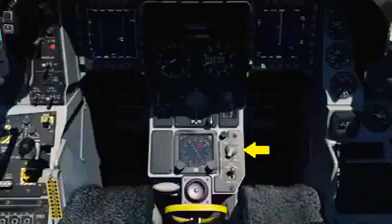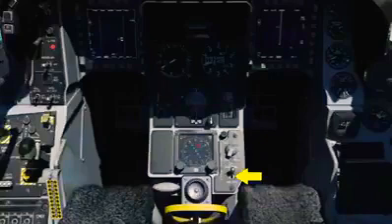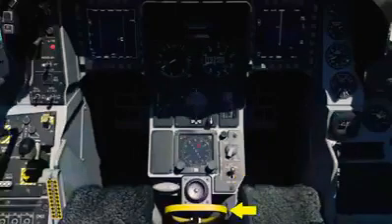Interior wing indicates the interior left and right external fuel tanks. Exterior wing indicates the fuel load in exterior external fuel tanks. The FR pointer indicates the center fuel tank load when set to exterior center. The external fuel transfer switch allows you to transfer fuel first to the center tank and then the wing tanks in the norm position, or to the wing tanks and then the center tank in the wing first position. The pull to eject handle is located in front of the seat, and when pulled, it jettisons the canopy and then starts the seat ejection sequence.